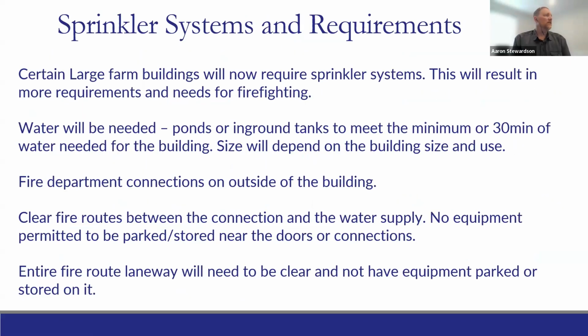So sprinkler systems, so certain large farm buildings will now require sprinkler systems. This will result in more requirements needing for firefighting, right? The biggest thing with sprinkler systems is you will need water on site. So again, ponds, in-ground tanks, and the size of this is required to be under the building code as the fire department needs approximately 30 minutes of water to start the fight for the fire, right?